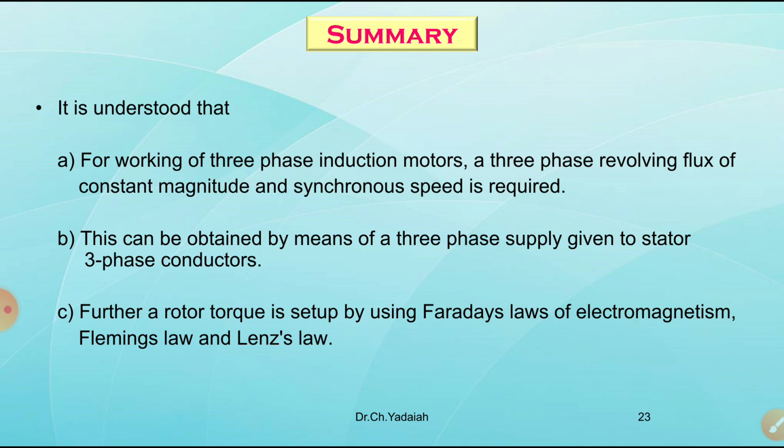At the same time, we also derived the frequency of the rotor conductors under standstill condition, under synchronous speed, and under slip speed. We have seen the relations between the rotor speed with respect to the space, the rotor magnetic field with respect to the rotor, and the rotor magnetic field with respect to the space.